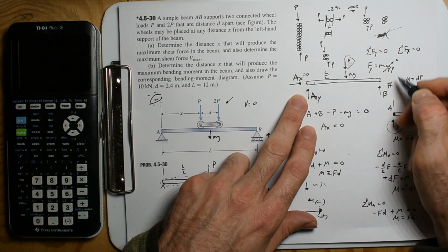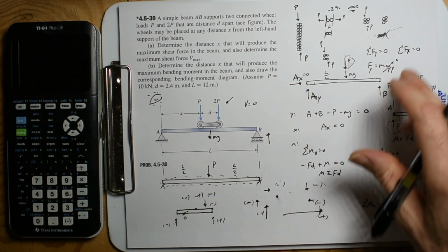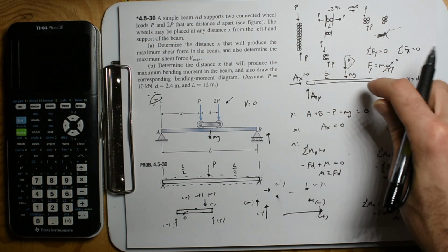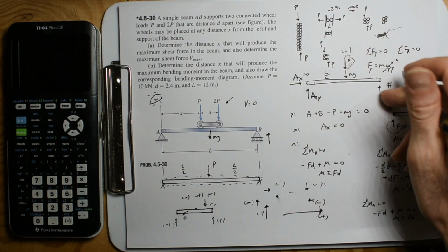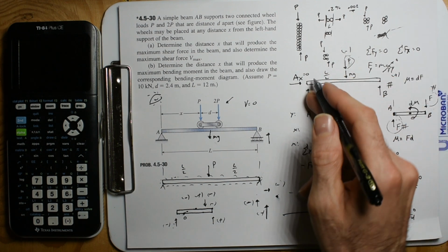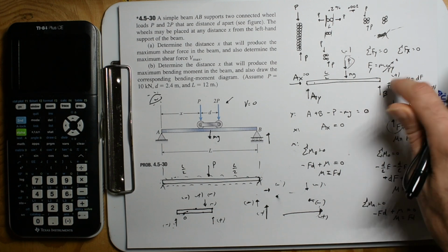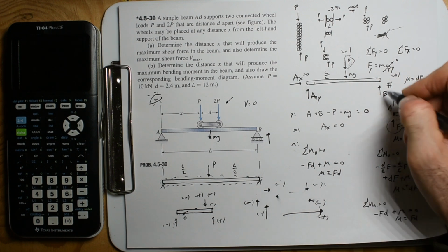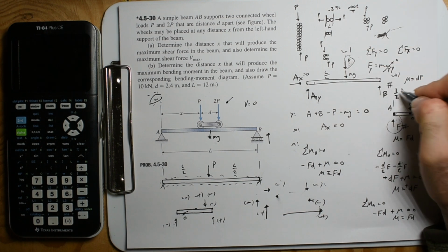There has to be a number on this force at twice the distance that's causing it to spin the other way, but balanced. So if this is a negative moment, this is going to be a positive moment, and because it's twice the distance, it's going to have twice the leverage, and the magnitude of this force is going to be half of that P. Cool.